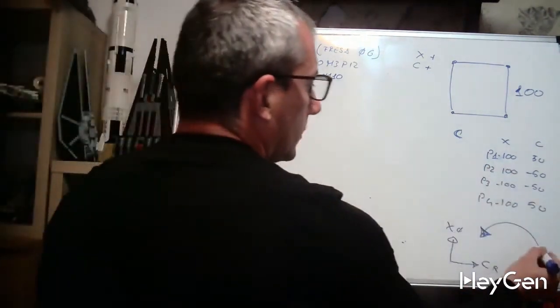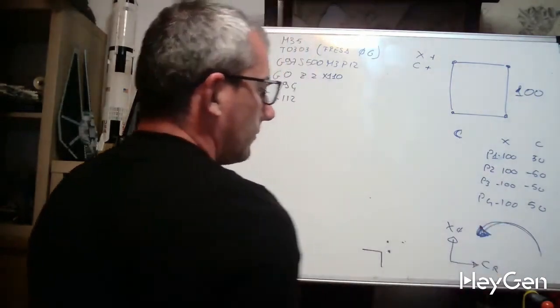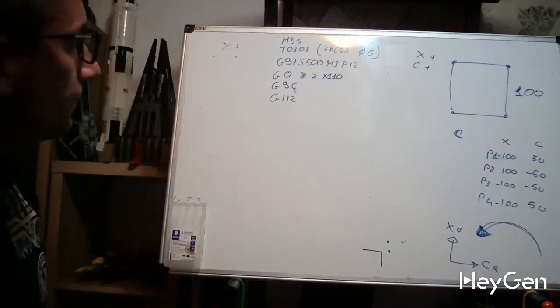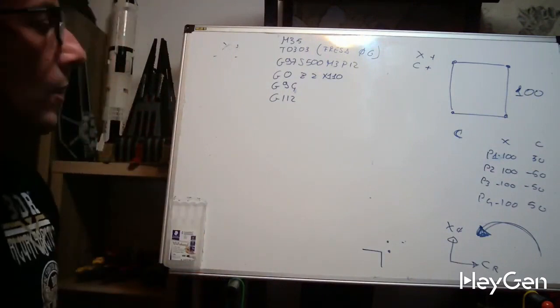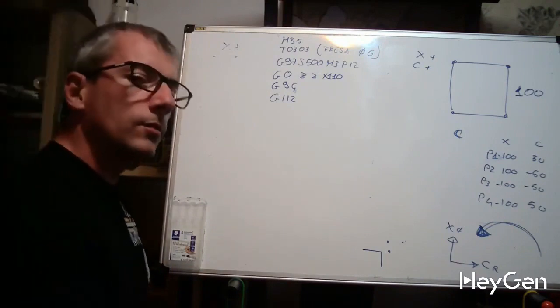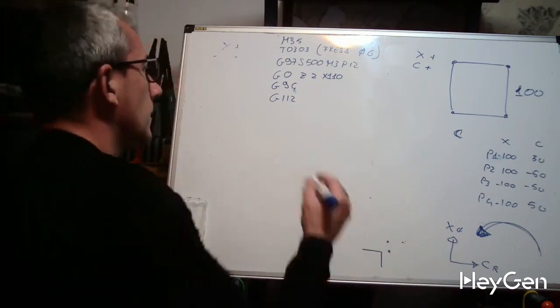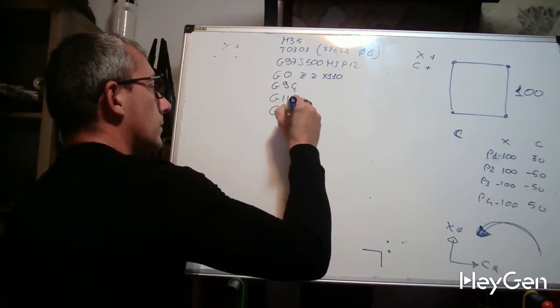Well, we calculated the points by working counterclockwise. When working counterclockwise, the same rule applies as for tool radius compensation, meaning that while moving around the piece in a counterclockwise direction, as previously mentioned, I will correct my radius using G42,